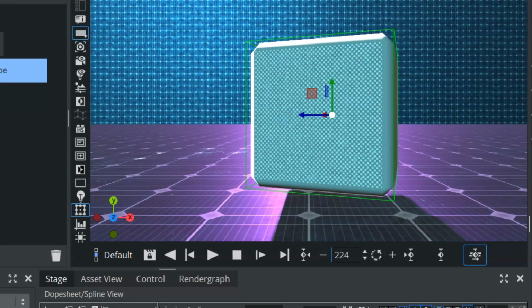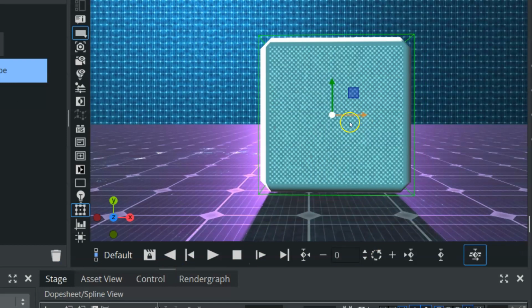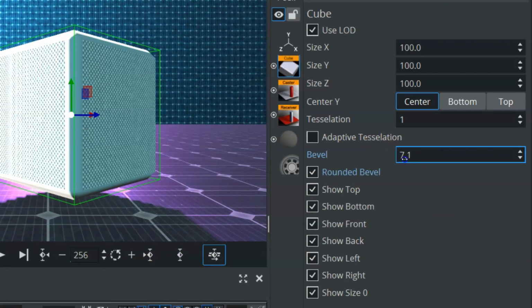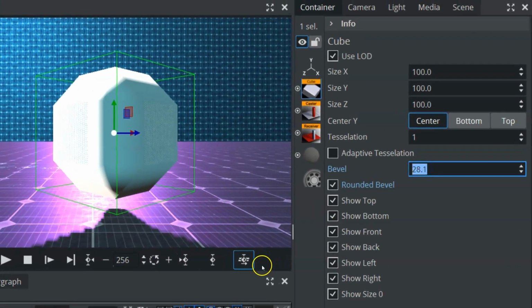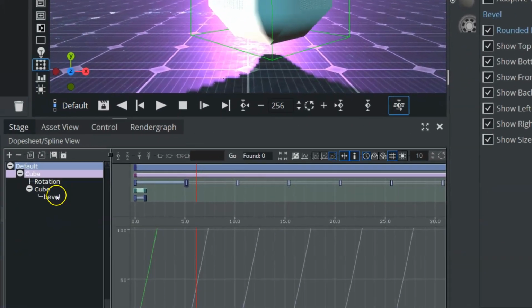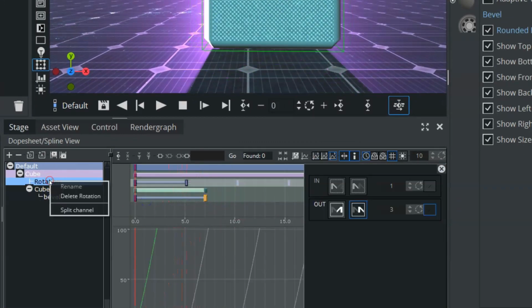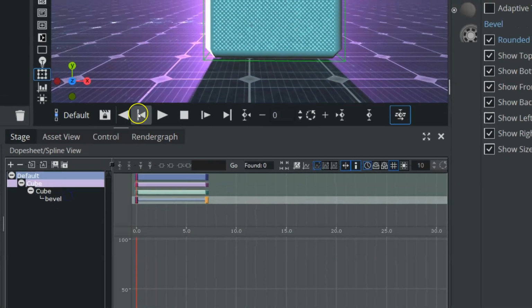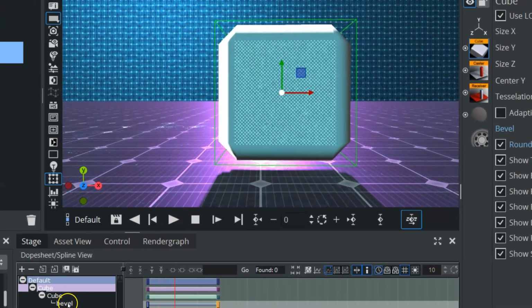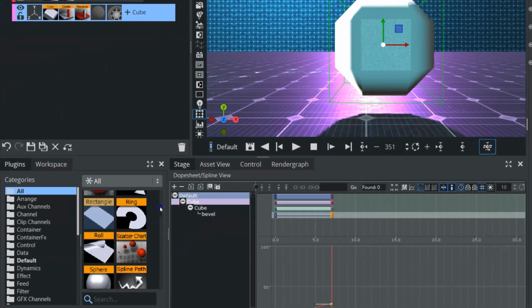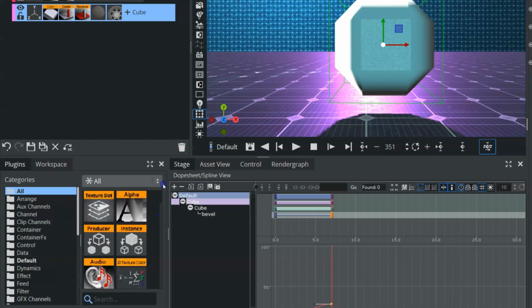As we mentioned in the basic animation tutorial, any variable can pretty much be animated within Vizrt T5. We have a cube here. So for instance, if we wanted to animate a particular part of this cube, we could. We have our cube options open here. I hit set keyframe, and if I wanted to adjust our tessellation of this, I could hit another keyframe, and that creates an animation down here. It tells us cube bevel, and then our keyframes are right here. So we could come in and delete our rotation animation and play, and now we just have a bevel animation on our cube.